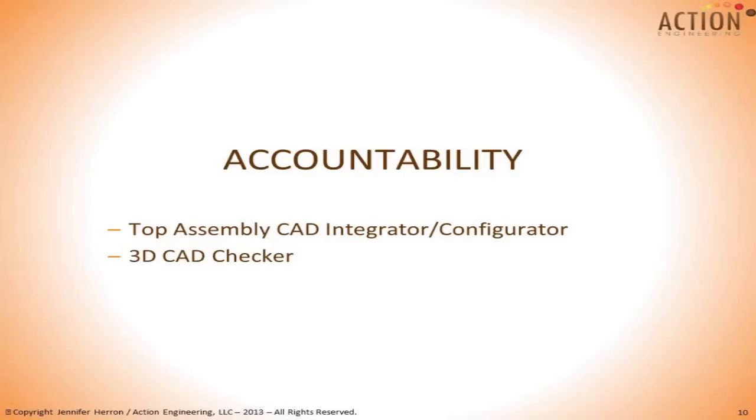Their primary responsibility is to make sure interfaces fit together. And in our case here with mass, make sure that each part has a mass, and that when it rolls up together, that assembly seems reasonably good, and maybe even they've performed some hand calculations to corroborate that,